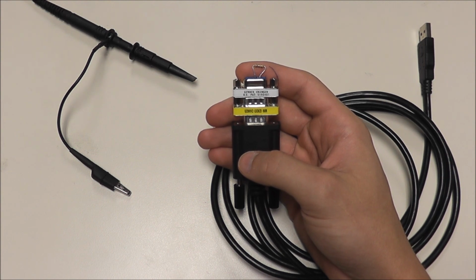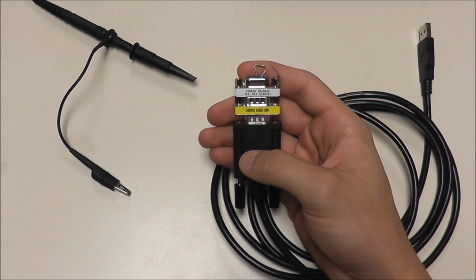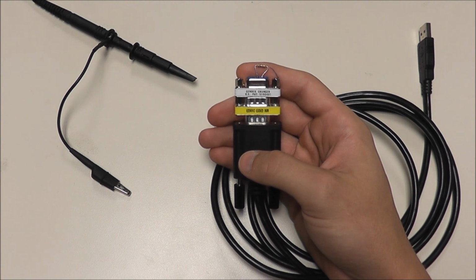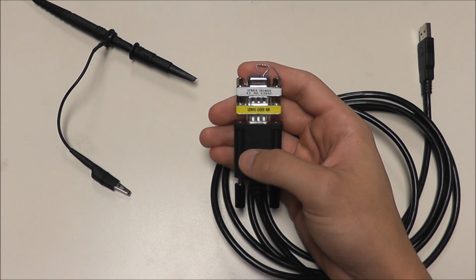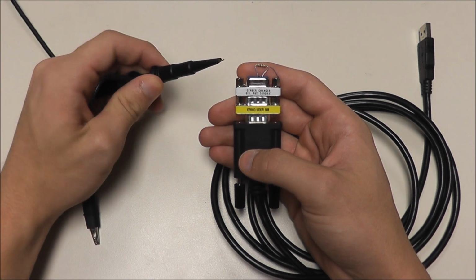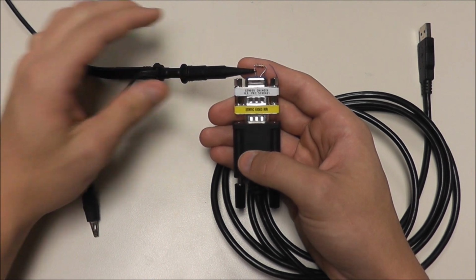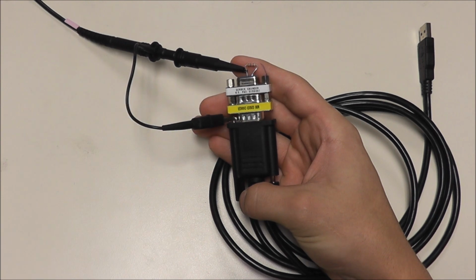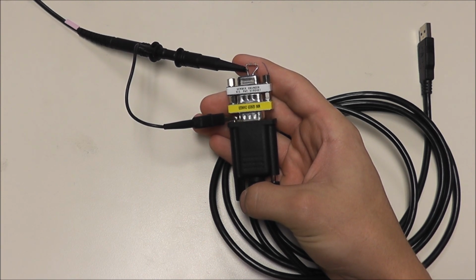As you can see, we have a USB to RS-232 cable and attached are a couple of mini gender changers with a resistor used to loop the signal. Because RS-232 uses single-ended signaling, we will need a single-ended probe. I will be using a TPP-1000 and I can probe anywhere here along the resistor, and I can ground anywhere that's not the resistor. And now we can connect our devices and proceed with our setup and decode a live signal.